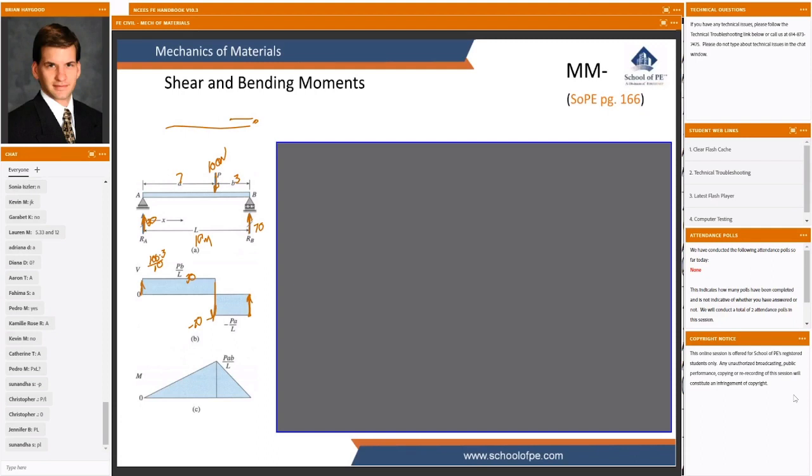That seems pretty reasonable. What is the total of this area under our shear diagram? We add up all that area, we're integrating that portion of the diagram to get our moment value. Our moment diagram is going to start with a slope of PB over L, whatever that means, a slope of 30 newtons, 30 newton meters per meter. And it's going to keep that slope all the way across to the 7 meter mark. So we know we're going to have a straight line there. Notice again, this horizontal line here gives us a straight angled line there, as it always will.